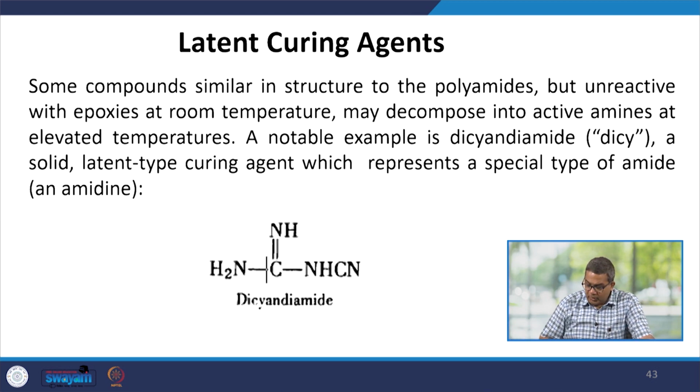Now let us talk about the latent curing agent. Some compounds similar in structure to the polyamides but unreactive with epoxies at room temperature may decompose into active amines at elevated temperature. A classical example is dicyandiamide, or DICY, a solid latent type of curing agent which represents a special type of an amidine.